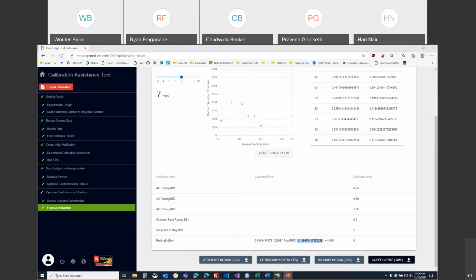And it just shows, like here, I would interpret this as my predicted rutting increases, the bias decreases, but it'll still affect your reliability equation, because it's based on the predicted rut. So here your rutting value should be a representation of your dispersion within your measured data and your residuals.